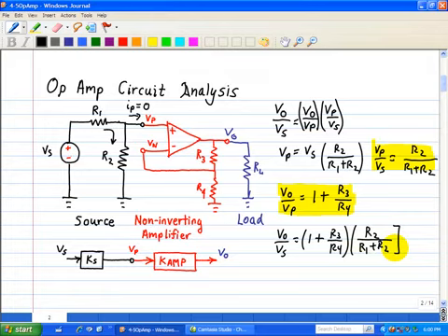And notice we had two factors concerning the product of what we call Ks, using the voltage divider. So here, that's just Ks, and then this relationship we've identified as K amp. And so we replace this circuit with this block diagram here, K amp, our non-inverting amplifier, and our voltage divider network here as Ks.